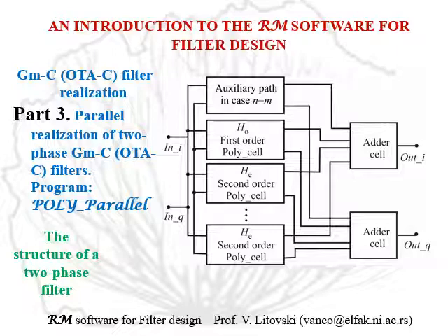In that way, one can produce a filter function which is translated on the omega axis and has a high attenuation for negative frequencies, which is not the case with the ordinary filters.